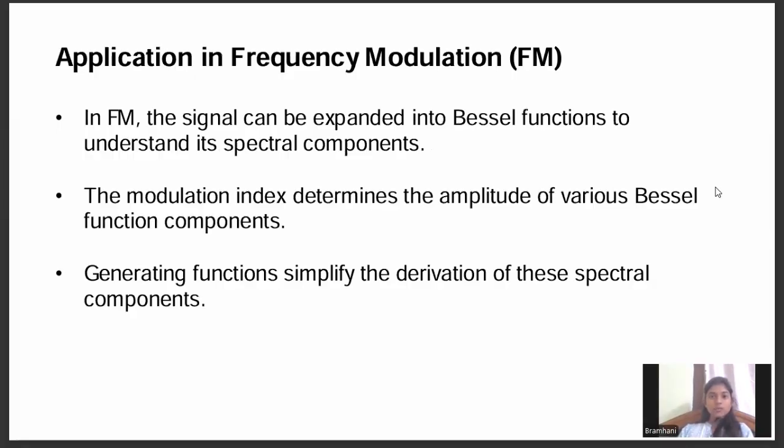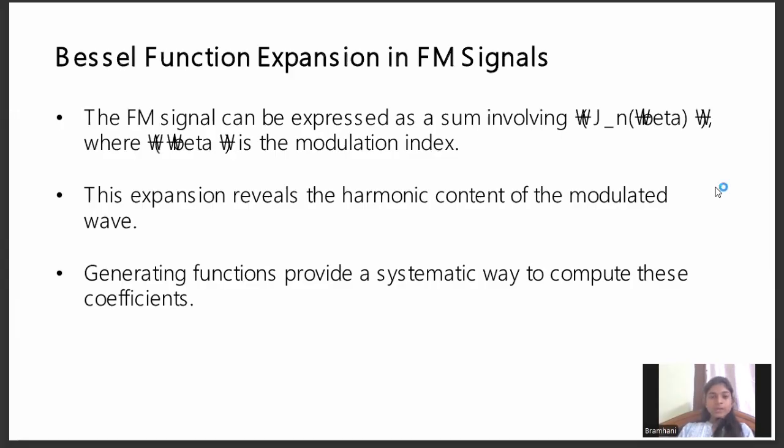Application in frequency modulation (FM). In FM, the signal can be expanded into Bessel functions to understand its spectral components. The modulation index determines the amplitude of various Bessel function components. Generating functions simplify the derivation of these spectral components.